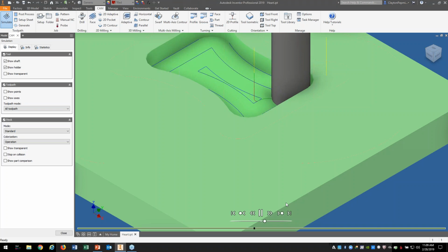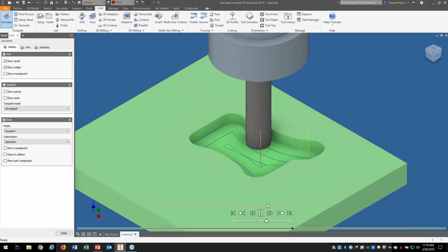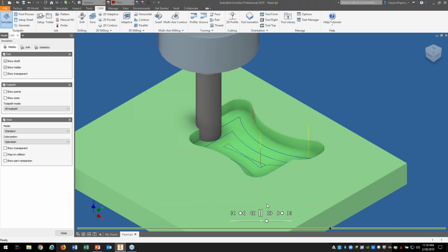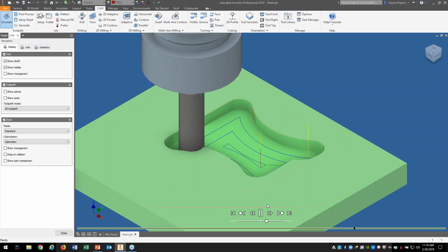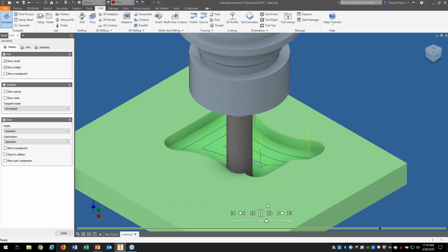This is what most software does when they get into machining: you give them a pocket or profile to follow. That's exactly what they do. They follow that profile. Again, you notice there's a full depth of cut there. You speed this up a little bit. Trying to keep this in the view to where you can see it. Again, all 4 corners, you're going to notice that tool is just literally burying itself. But the good news about this is I'm basically taking 1, 2, 3 laps around this pocket, and in 3 laps, I've got the pocket entirely cleared out.